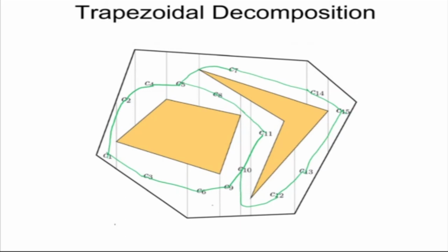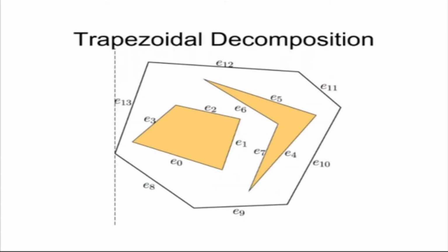Now if I want to find a path, I simply take the midpoints of those lines and connect them. That's the path which is going to be equidistant from the obstacle and the workspace, and that is going to give me a connected graph. Now, how do we run the algorithm?